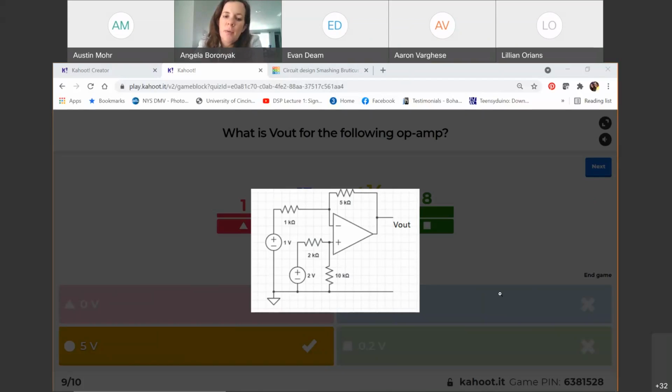It's actually a difference op amp, the one we learned yesterday. I have 2 voltage sources, and through resistors, they connect to each input, my non-inverting and my inverting. So that was step 1. Or I can use my general op amp rules, but it's a lot harder for this one. This can have current going this way, this one can have current going this way. If I find my voltage at this midpoint here, then it has to be the same voltage here. I can find that by voltage divider because these two would be in series. No current here. Find the voltage here and then find V out, but it's kind of a giant pain to do that.